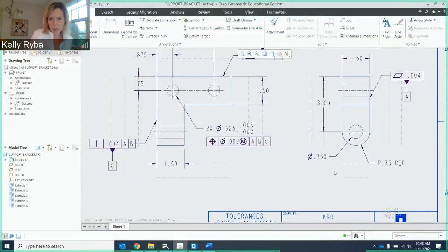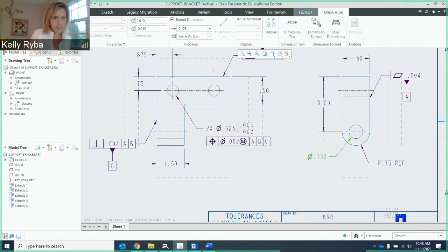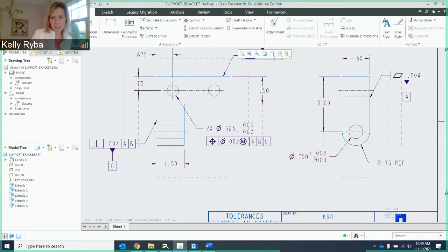And we're gonna first look at the tolerance here, and we need this to be a tolerance plus minus, and we want it to be plus 0.008, and then minus 0. Here we go. Oh, not 10,000s, minus 0. When I click up here, it should be okay. All right. I think that's all I need there, right? There's only one of them, so that should be good.